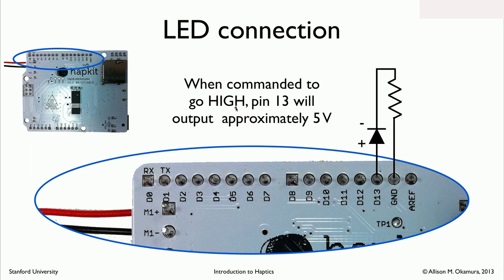All right, so what we want to do then, in order to generate light from our LED, is hook up a circuit like this. So we've got our LED over here, and we've got our resistor over here. And you see that I've carefully drawn this circuit and defined the positive, the anode, and negative cathode of the LED such that the current that's flowing through it is going to be going in the right direction to light up the LED. So the current is going to flow this way.